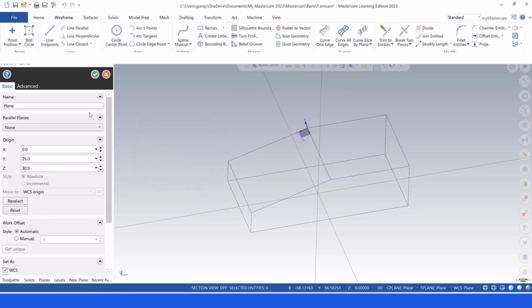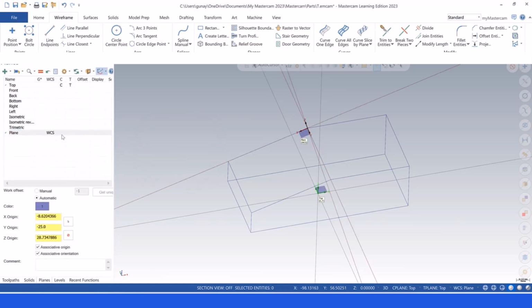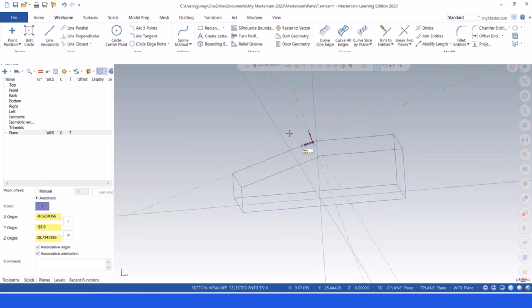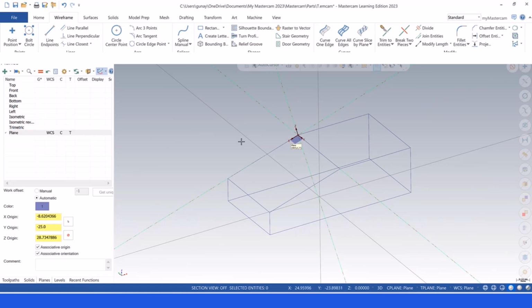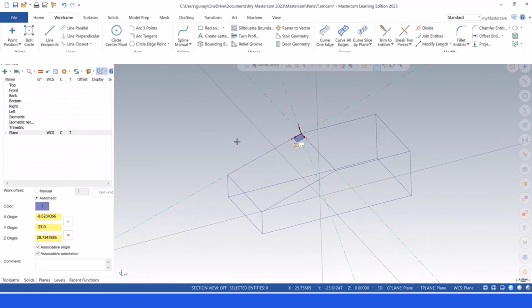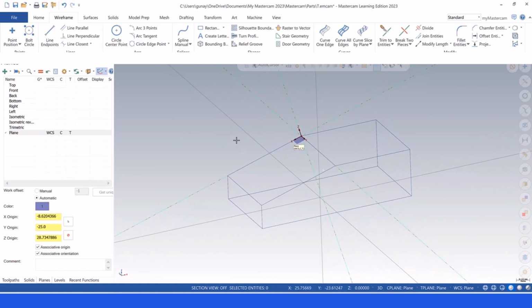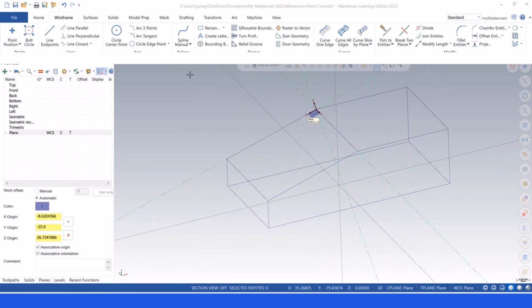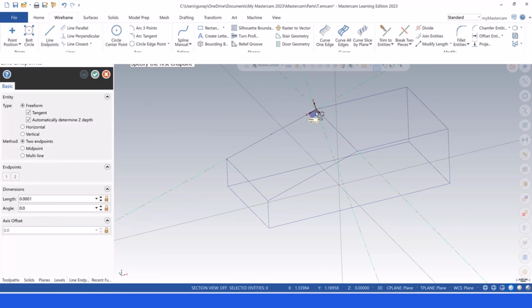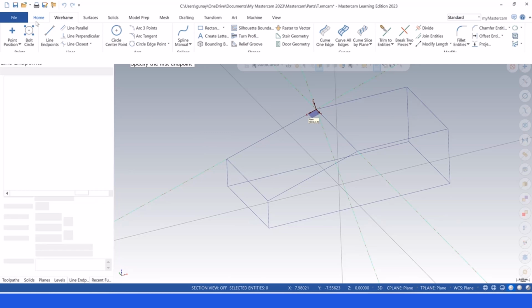I'm gonna hit that button and that button. After that, we can easily turn to C plane and tool plane here, and then you can also see that it is easy for us to create some other geometry here. For example, this is the C plane.